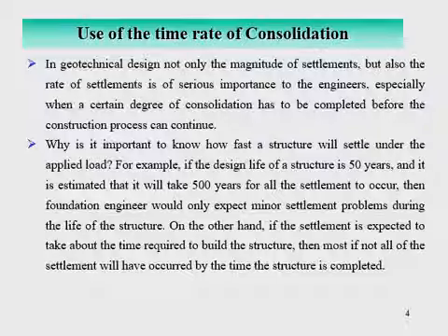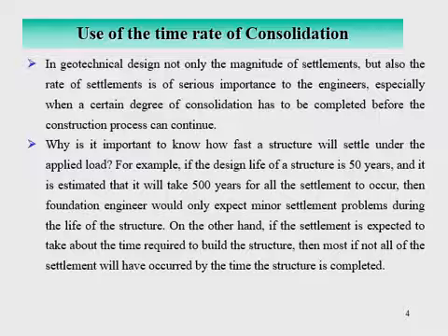Why is it important to find time rate of consolidation? You see, if the design life of your structure is 50 years and your calculation shows that final consolidation settlement occurs after 500 years, right? So why design your foundation or building for a settlement which would complete in 500 years?